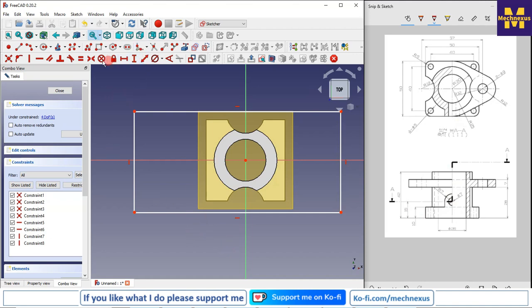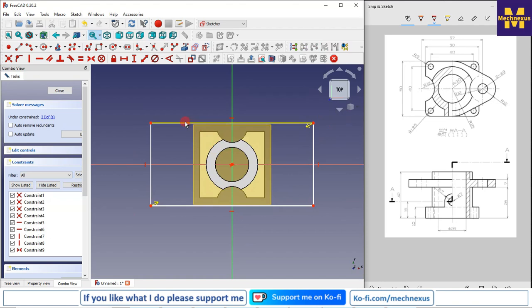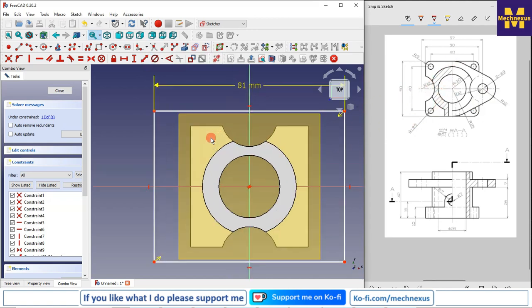So I will first make it symmetric. I will select this point and my origin point. Now I will select this line and give my dimension. So it will be 57 plus 12 plus 12 because this R12 is on both sides, and this is the 50.